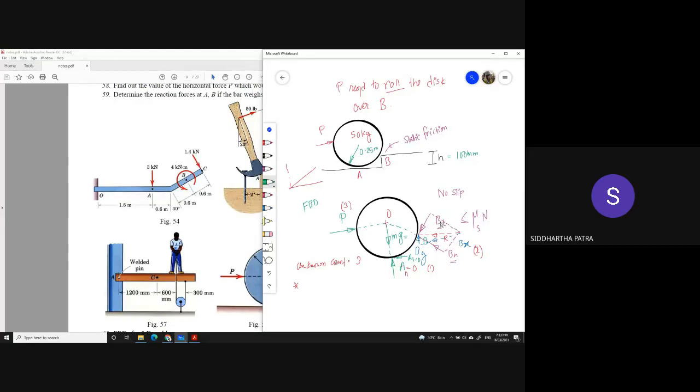Instead of Bt and Bn representation, you can go ahead with Bx and By representation. Then there are two unknown components, Bx and By. But after solving the equilibrium problem, because the net moment about O should be zero, you'd get that this Bx and By act radially, which would basically mean the component Bt itself is zero. But that's just the solution. Using that in the free body diagram would render the free body diagram useless.